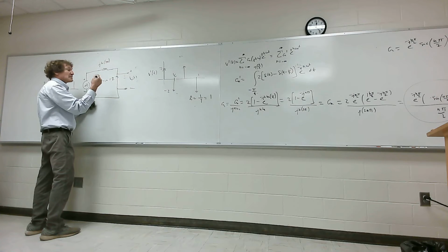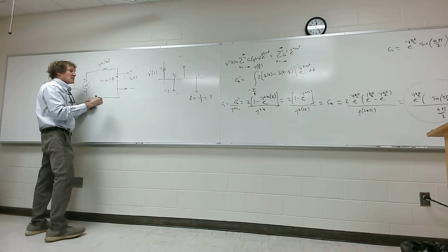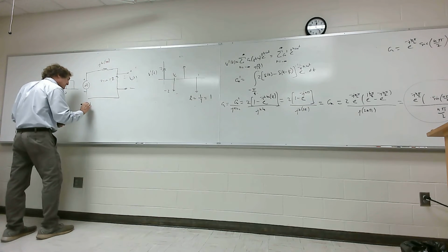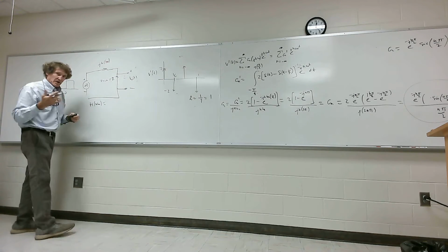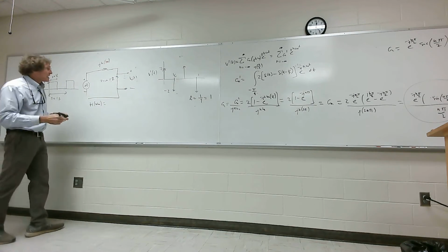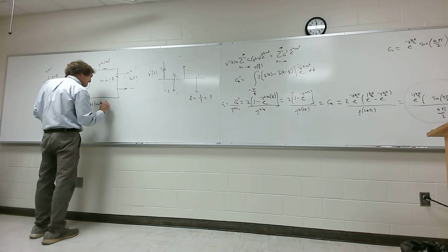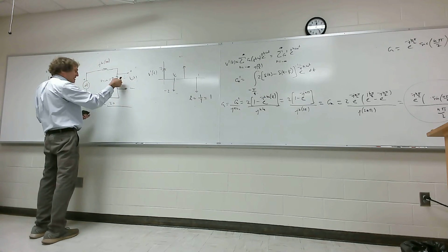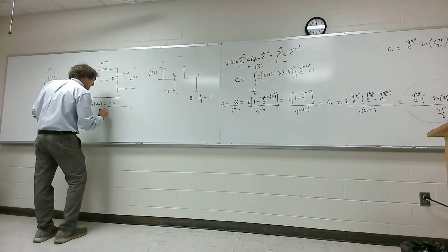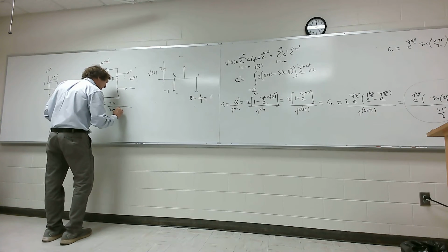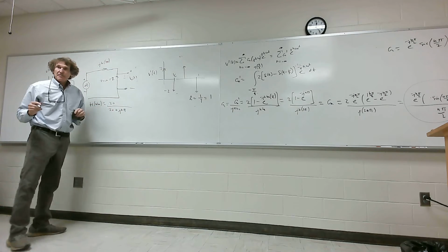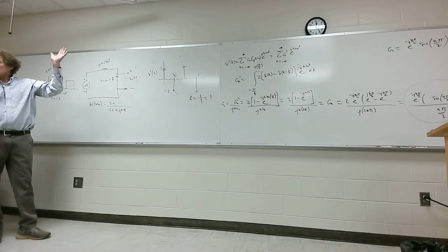So I have that times 1 is the impedance, and if I want the actual H function, what is it? H of n omega naught, or H of n times 2 pi. That's the output impedance, which is 20, or the load, you might say, over 20 plus, and this is going to be j n pi. You all agree with that? How many see this? You okay with it? Don't let it scare you.